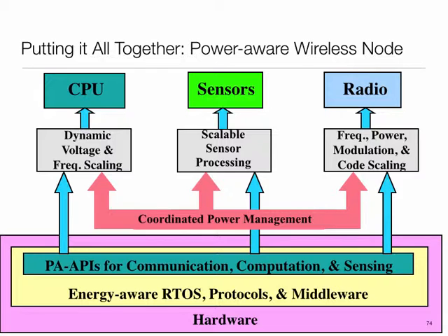But what am I losing? I'm losing in the information content. I cannot capture information in certain frequencies now. So if you think of my spectrum, if I'm sampling at rate X, the bandwidth I'm going to cover is X over 2, and therefore I'm going to be missing out any information above that. I also obviously have to filter.